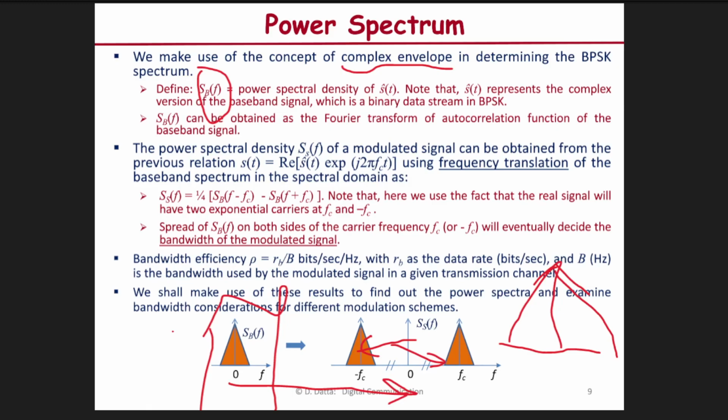WK theorem, Wiener-Khinchin theorem. If you have a random signal, you cannot take the Fourier transform. If it is a deterministic signal, say a single pulse, then you can take the Fourier transform, take the magnitude square, and get the energy spectral density. But if it's a random signal, how can you take the Fourier transform? Because you cannot choose a time segment, because it is varying with time.